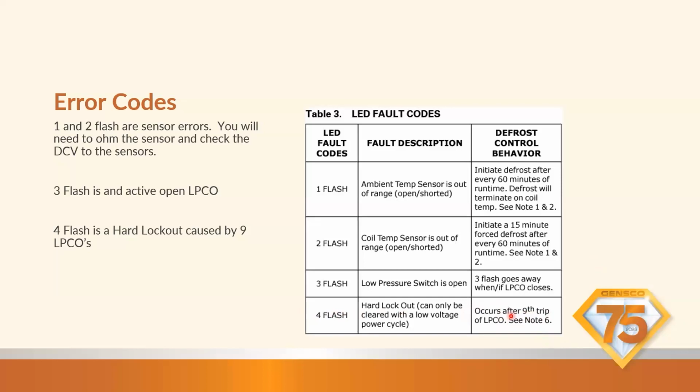Low pressure problems can be caused by airflow. They can be caused by refrigerant. They can be caused by people running it at improper conditions. So if you have a homeowner who's trying to cool the house to 60 degrees when it's 40 degrees outside, you might get a low pressure trip. That can happen.